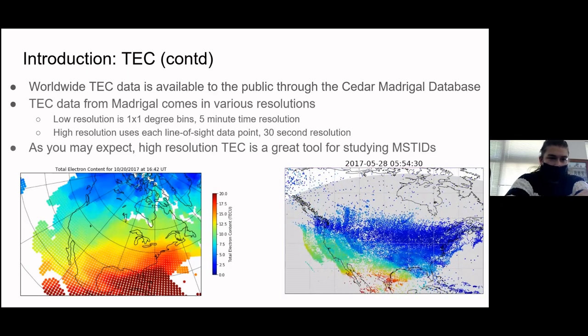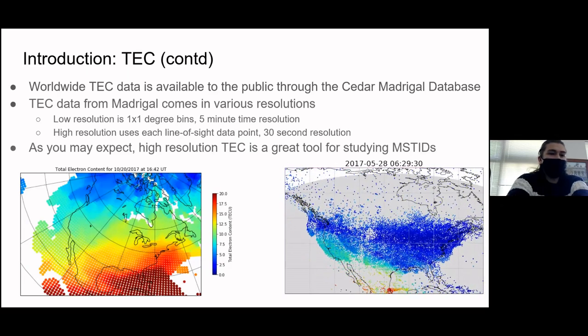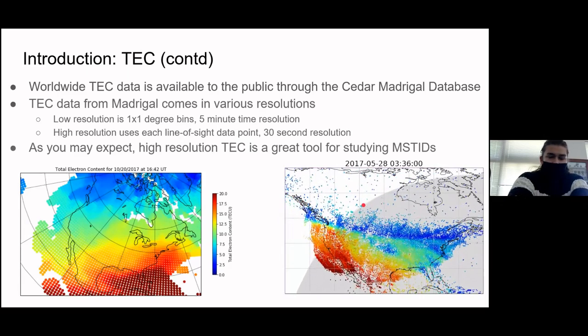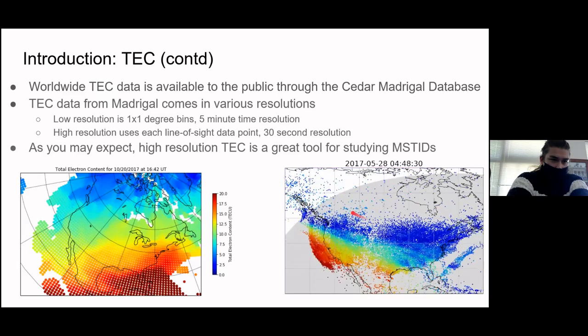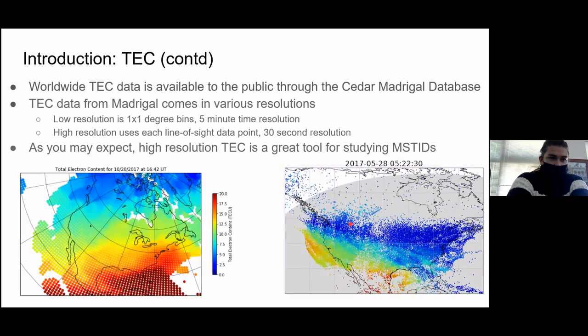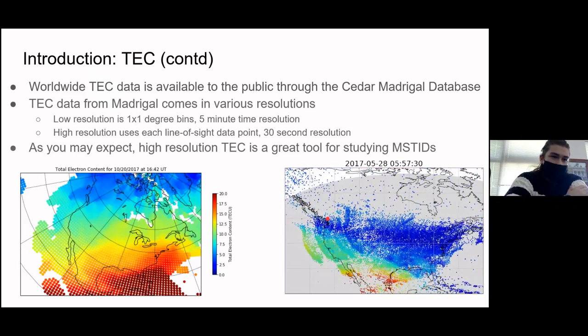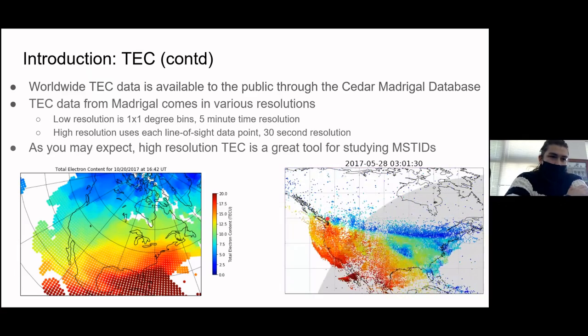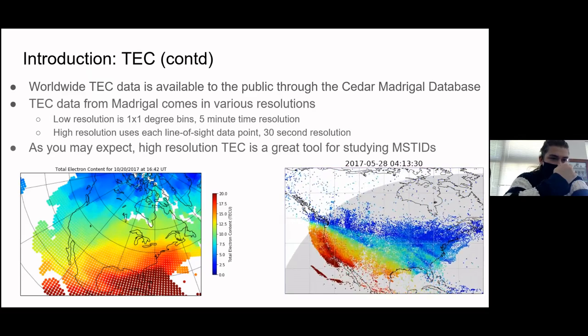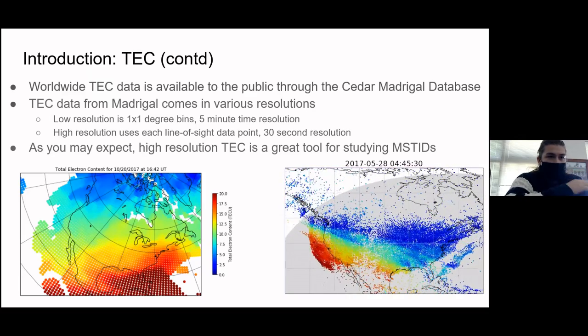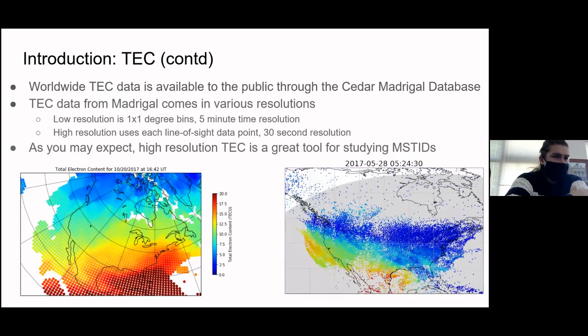And you can see you have thousands and thousands of individual points. Each point is a satellite receiver pair. So you have thousands just over the US. And these wave fronts you see moving across, that's when the satellite comes within view of the receivers. And also, I should say that anything with a low elevation angle is thrown out. You don't want any oblique paths to the ionosphere.